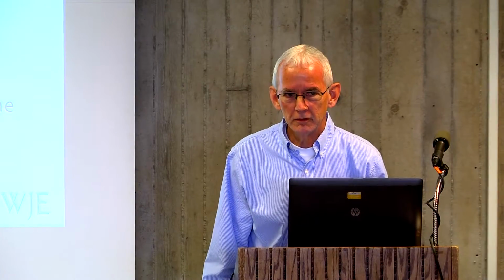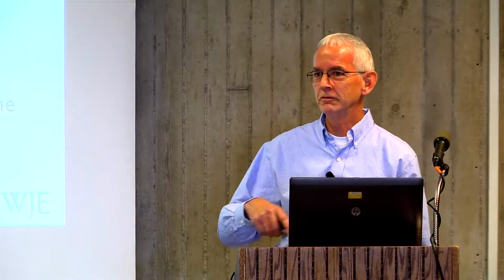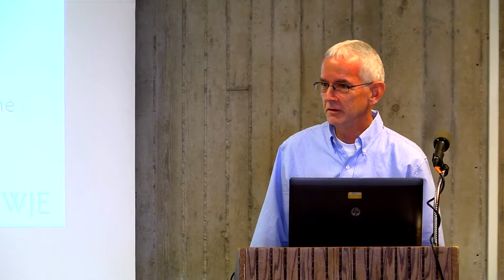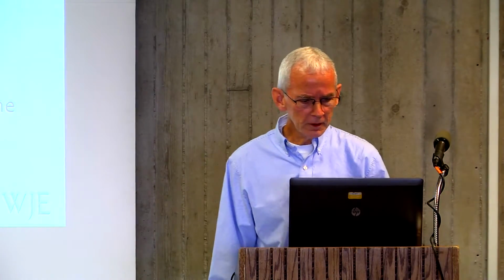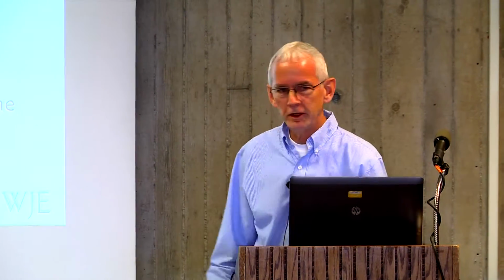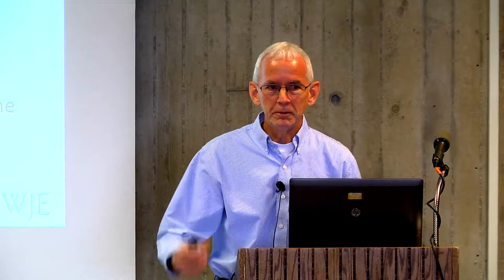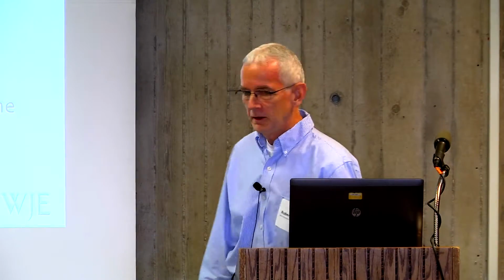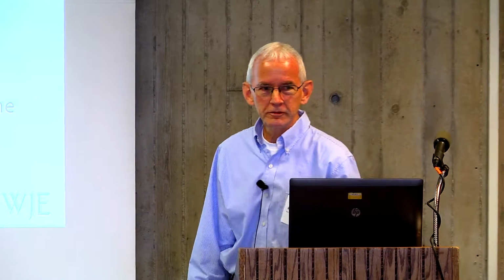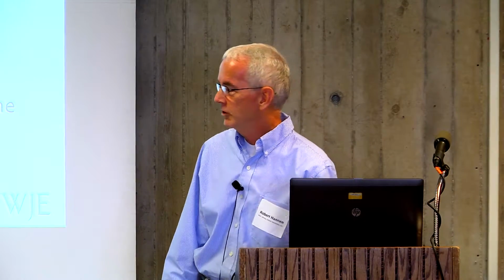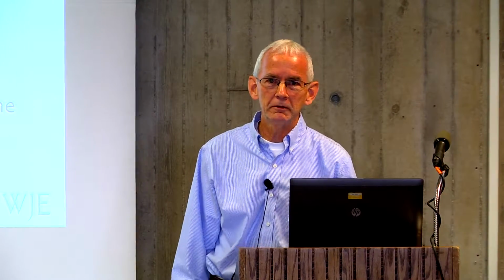The next day they discovered that there was movement that had occurred in the building. The surveyor went to do his normal circuit of elevation surveys and found that he couldn't get into a bike room that was right up adjacent to the wall next to the construction work. They did the pounding on a Thursday. Friday is when they discovered that they couldn't get into this room. By Monday, the stairwell that went up adjacent to that wall was starting to exhibit some relatively significant spalling of the plaster finishes, and it looked like the stairwell was getting twisted apart.